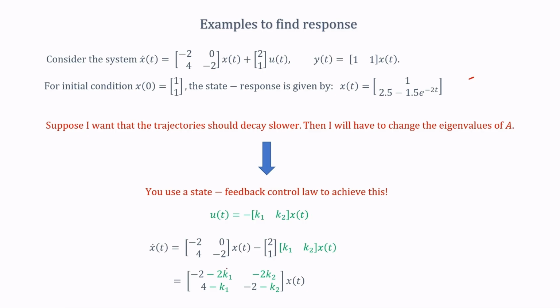Now, notice k1 and k2 can be changed arbitrarily, it is in our hands, right. So, I can go ahead and change the values of k1 and k2. If I change the values of k1 and k2, the eigenvalues of this matrix will change, right, and that is what we wanted to do.